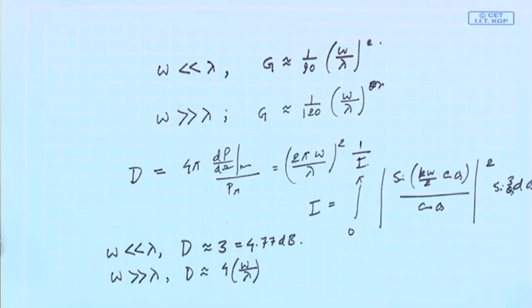So, that is why it is not much, and there are methods by which people, using higher dielectric constant substrate or increasing the thickness of the substrate, or cutting holes or slots into it, or adding reactive components, etc. Various people make it better and better.